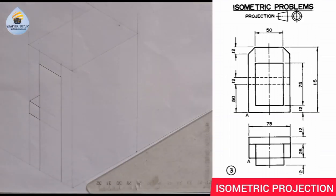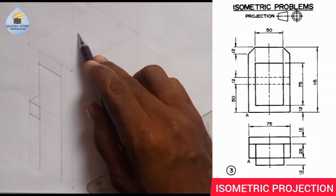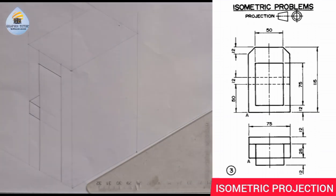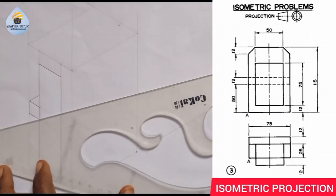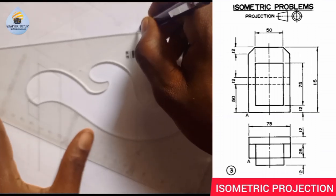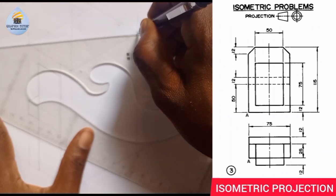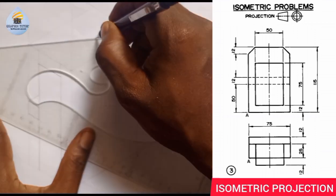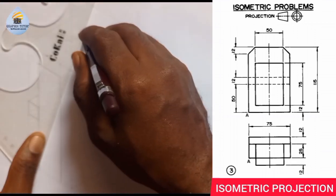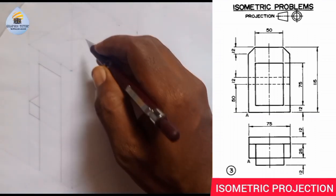Right? Now the next thing is the thickness at the top here. This top, from here to here, is 50. So I have to get the center of this rectangular shape here, right? So how would I get the center? The easiest way to get the center is to join the diagonals. So join these diagonals from here to here, just a little bit, and from here to here, just a little bit. That is where they are meeting, so that will be the center.